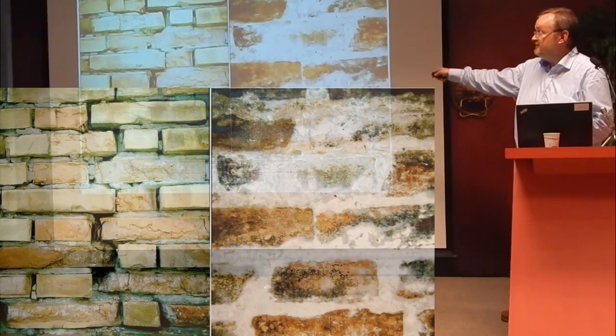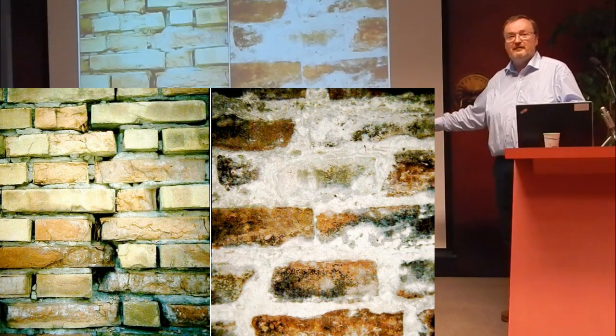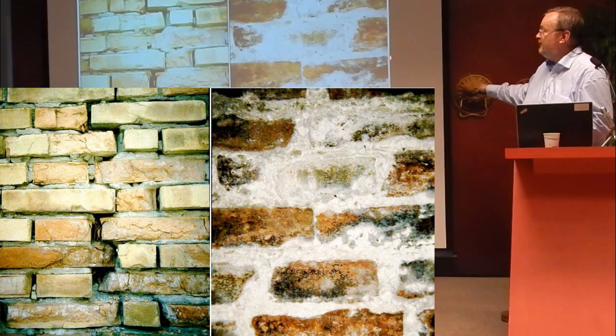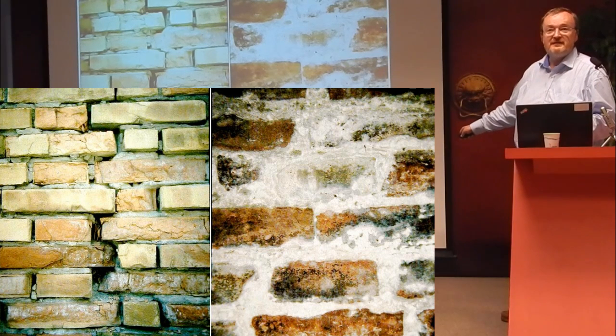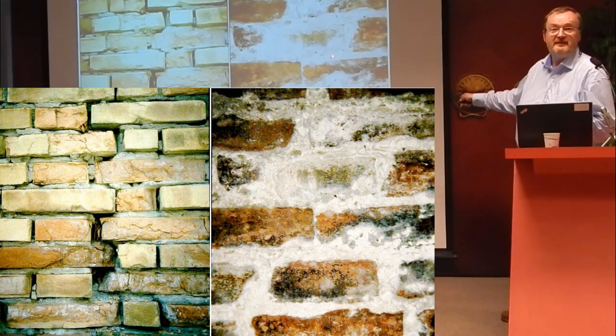As a result, this is a cement mortar after 10 years in Italy, in the city of Rimini. And I found this: a 400 year old lime mortar facade of the Gothic church in Rimini. It doesn't look so aesthetic, but it has no cracks and it works.